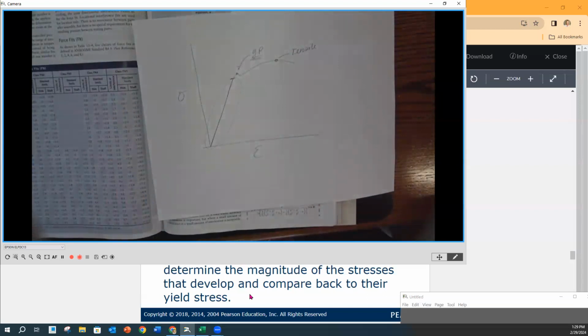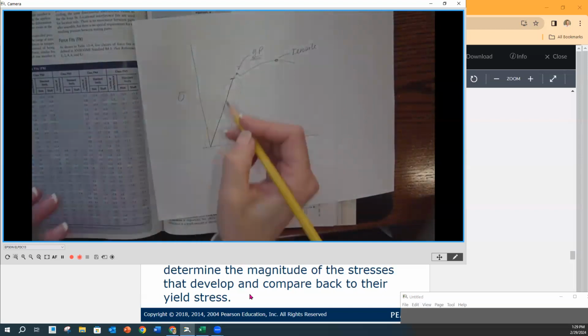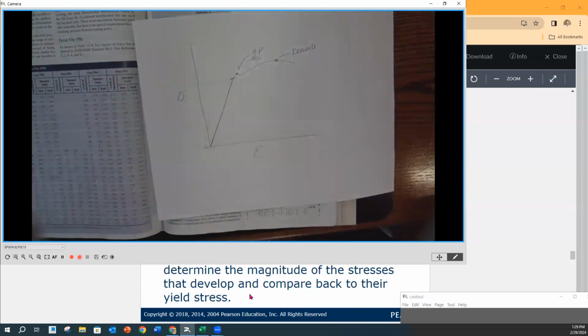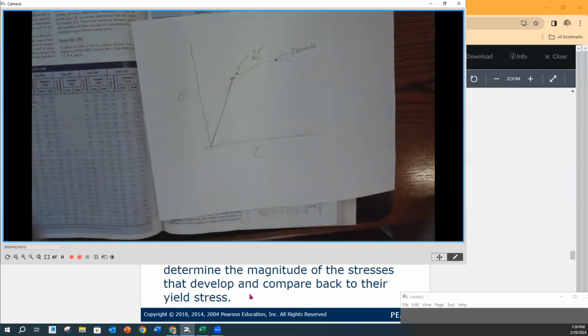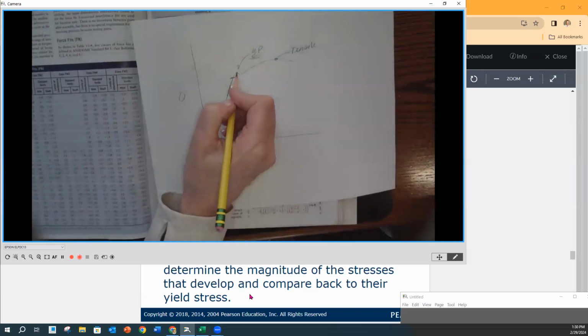and this yield point, technically, this is actually failure, because now what we've done is we permanently deformed it 0.2%. Doesn't sound like much, but we have. And what happens at this point is that the internal grain structures no longer are going to perform mechanically like they did down here. Down here, that steel is the way it was supposed to act, okay? When I pull it apart, it bounces back. Pull it apart, bounce it back. We keep putting more and more on it. And then when it doesn't start bouncing back, we start seeing that.